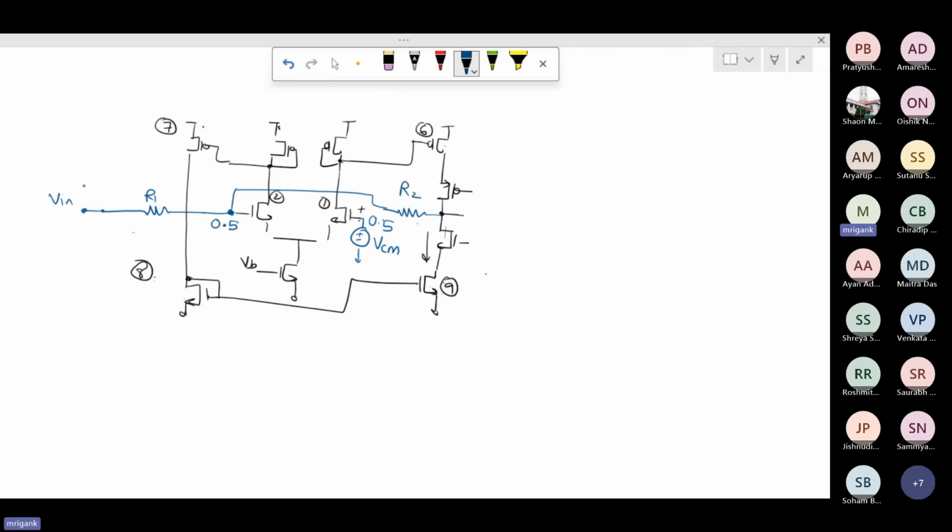So in this case, when you are applying resistive feedback, how will we decide what is the signal swing available at the output, and also what is the input range here? Suppose the gain R2 by R1 is big, say 20, or suppose 100.